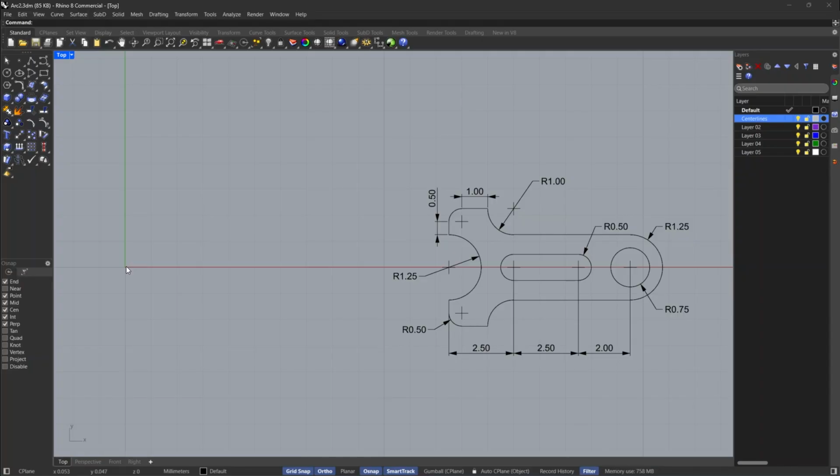Now, you'll notice that I've drawn a completed and annotated model on the right-hand side for reference. We will start this model by drawing center lines. Then we will use the intersection points of these center lines to draw our arcs and curves. We will draw this model using only object snaps and the line, circle, and arc commands.